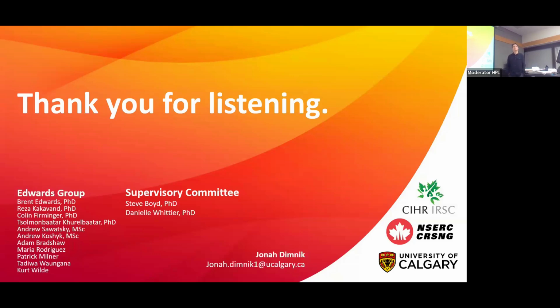Let me make a suggestion about your loading, which is that maybe you should intentionally do it wrong. I'm assuming at the bottom you're doing some sort of fixed. Okay, so it's fixed, so you can sustain moments there. So rather than trying to go straight down the bone, intentionally go in a direction opposite to where your strain gauge is, so then you're going to maximize your compression.